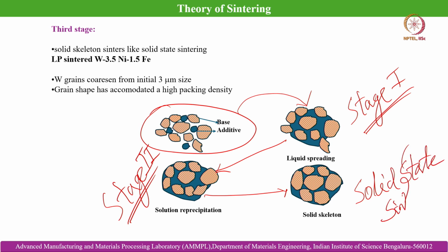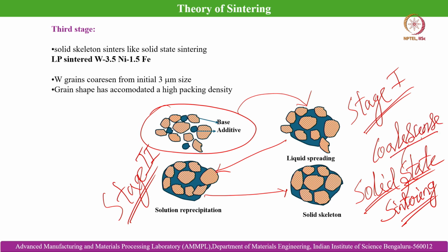Here the second coarsening mechanism, or mass transport mechanism, that is coalescence, becomes prevalent. You can see that the point of contact is established. From there the neck forms between the particles and grows, and then they become fully diffused into each other, and then we see the formation of grains in the sintered compact. This example is shown in the case of tungsten nickel iron alloy powder.